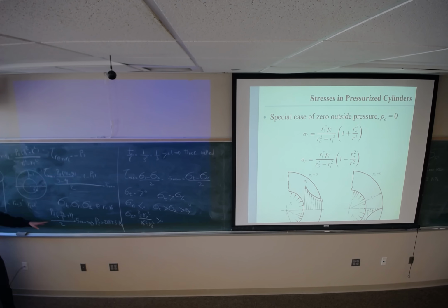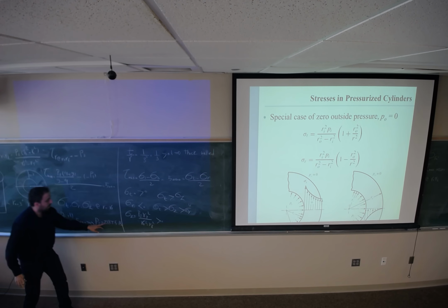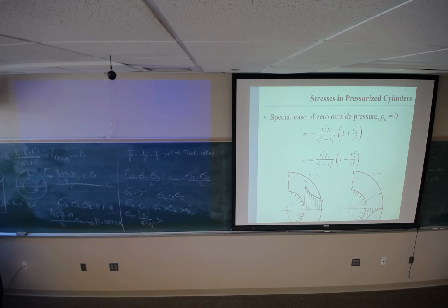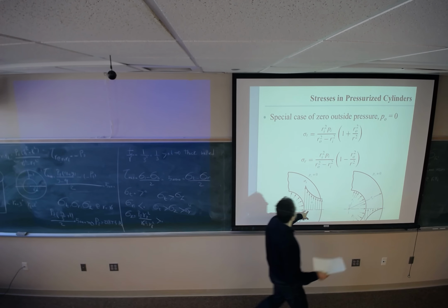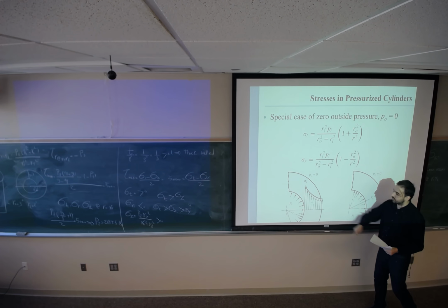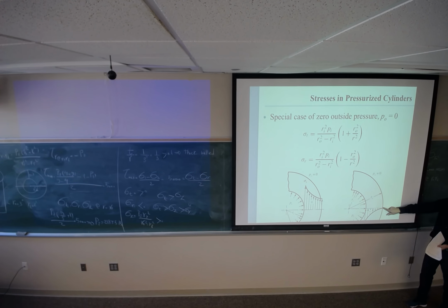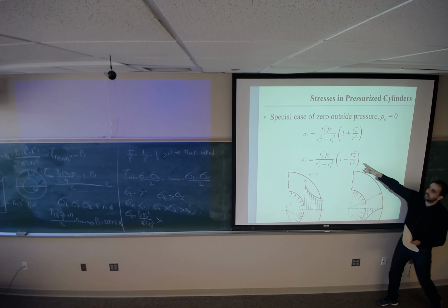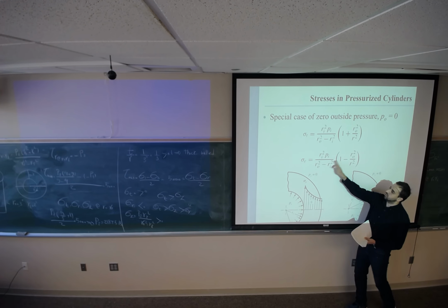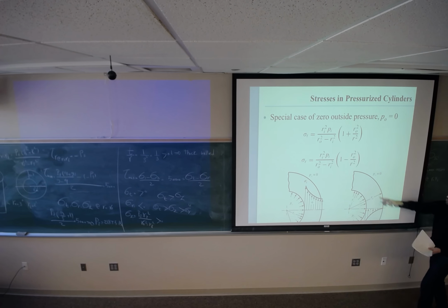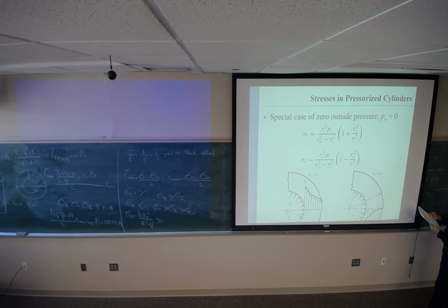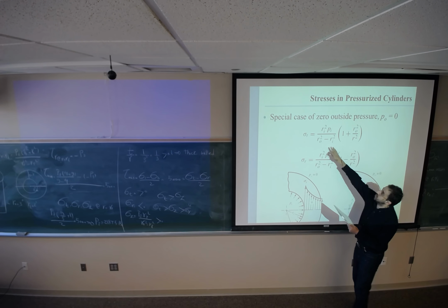After we find this D, I ask you to find the stress terms at the outer radius. This means at r equals R_o. As you see, for radial stress it's going to be 0, but if you want you can check. Just plug in r equals R_o, do the math, and you will get 1 minus 1, which is 0. Find the sigma_T at r equals 3 inch. It's just plugging the numbers in.